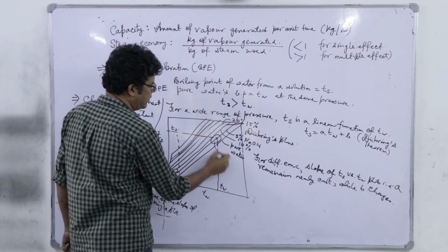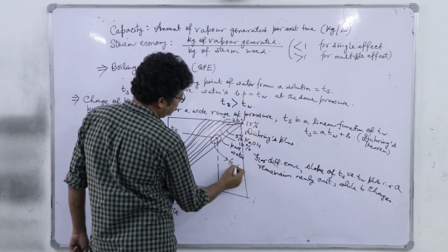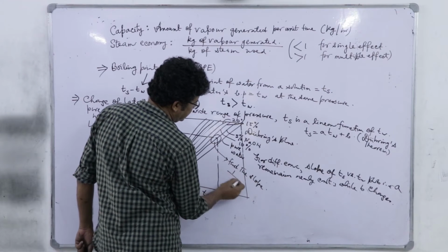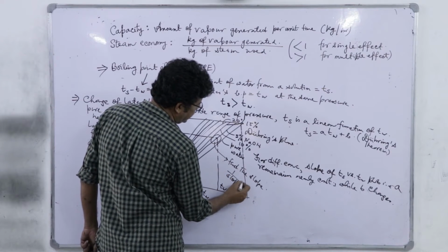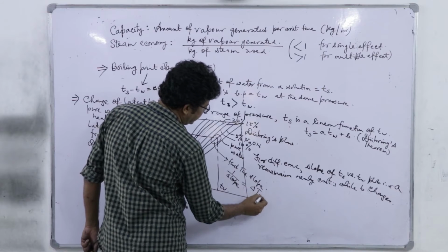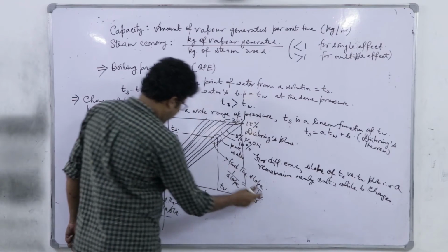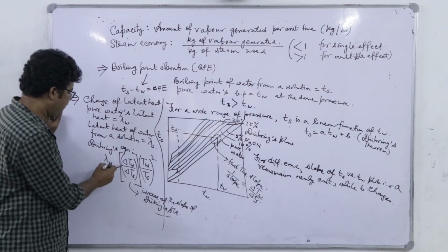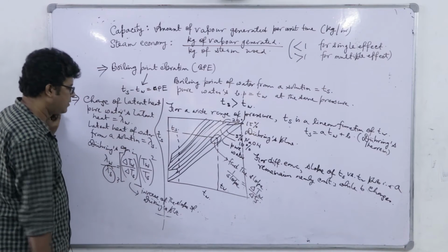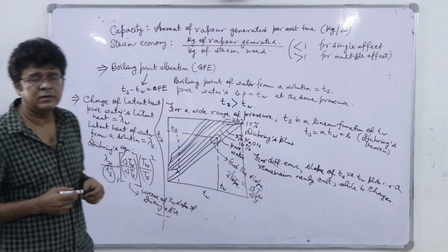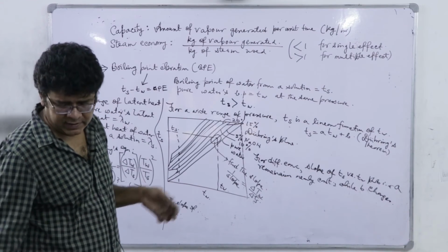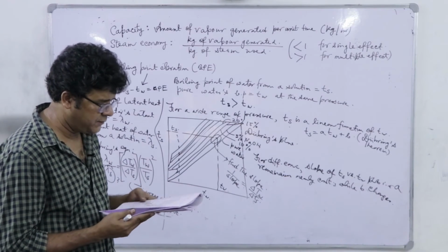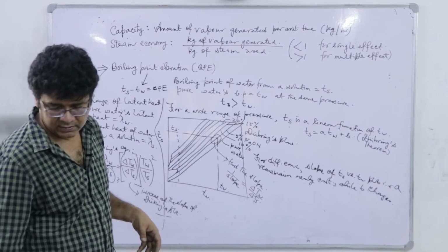So here we can find the slope, right. So 1 by slope is equal to delta TW by delta TS, and that we will directly substitute here. We know lambda W, so we can find out lambda S, right. So this is Duhring's equation. Similarly, the alternative equation is the Othmer equation, but Duhring's equation is fairly accurate for different types of systems, right.